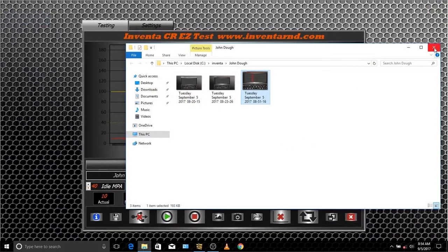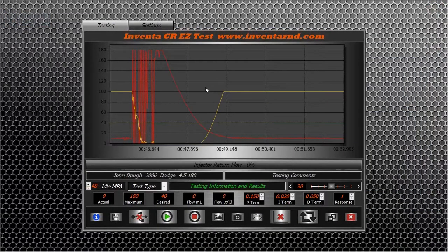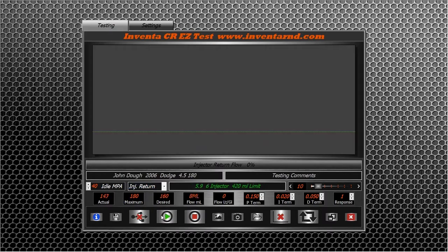Or let's say your customer is really busy. He's a businessman, and he's in meetings all day long. He's really hard to get a hold of. But he says, if you send me a text message, I'll respond back to you. So you don't have time to really explain things. So you send him a screenshot, and we've run an injector test. Let's go ahead and see if we can make one come up here that fails. Oh, okay, we failed. So we're over limit on our injector return.